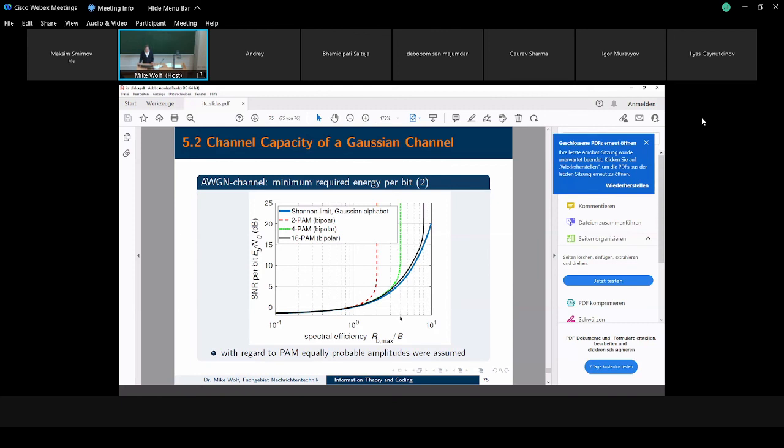But the interesting thing is the theoretical limit at very low bit rates, which means you have a lot of redundancy or coding, can still be achieved if you have a binary distribution. And this is often used. So if you are interested to transmit at a very low transmit power or energy per bit, you just use binary transmission.